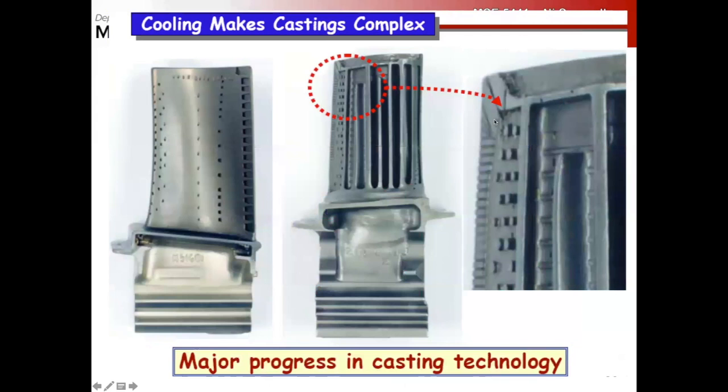Here's what the castings look like, the cooling channel, right? You have two air channels that come in down here, that force cooling air in, out through these holes, which then gives you a thin film of cool air on the surface. The idea is you want laminar flow of cooling air across that blade. But this is just really, really complicated internals.